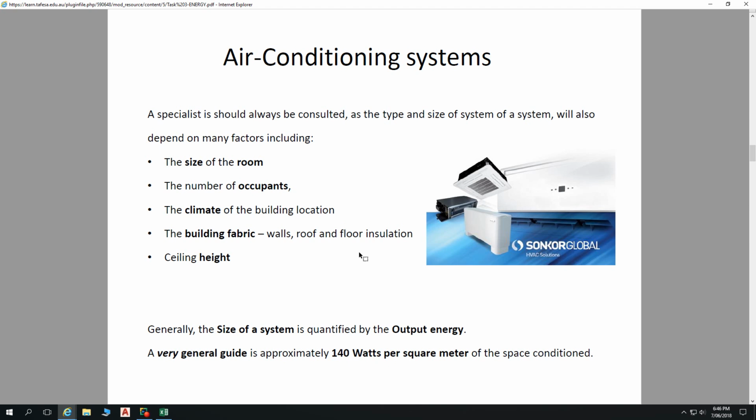So some of the things that are being considered there for the building fabric are thermal mass and the impact of thermal mass, and how appropriate that thermal mass is within the building, whether it's helping the air conditioner by stabilising the air temperature, or whether it's a very solid west facing wall which is taking in a lot of heat and then emitting a lot of heat into the room. So it's about the building fabric and the impact of that, but then also about how much heat is transmitted through the walls. So what are the R values of various different materials and insulation.